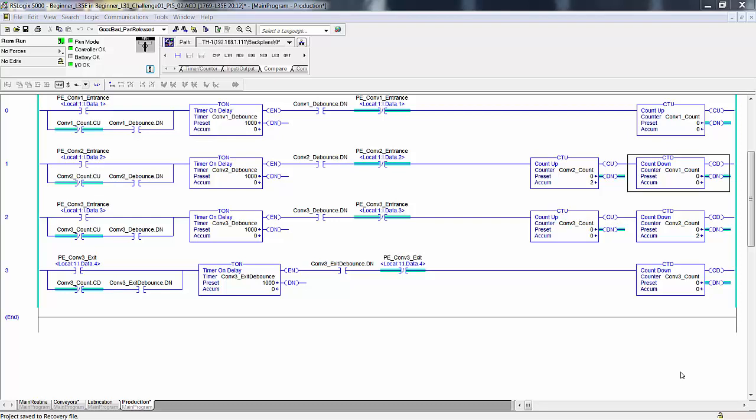Then it goes to the body designer, and he looks at it and says, well, there's no way in the world that we can stamp out of sheet metal those door panels, hood panels, trunk panels, roof panels, fenders, etc. There's no way in the world we can do that in a stamping press in this day and age with our current technology. So he modifies the design to accommodate practical sheet metal work.